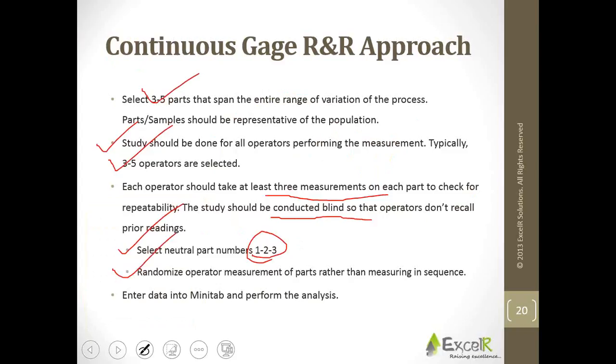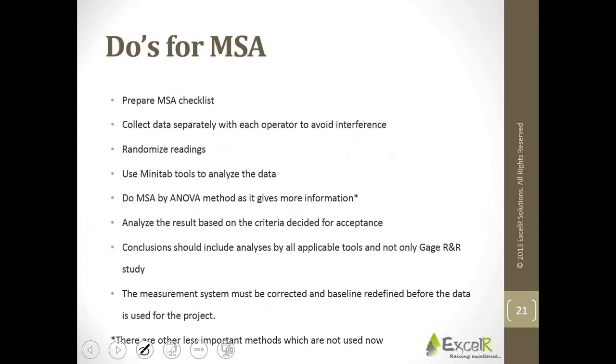And then randomize operator measurement of parts rather than measuring in sequence. Randomize means once they take the measurements, put them in a random order. Then you can probably use Minitab and perform the analysis.